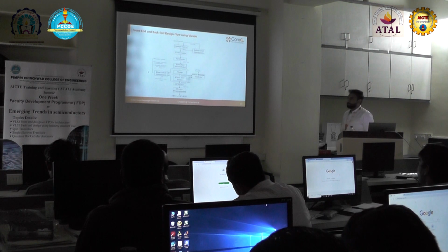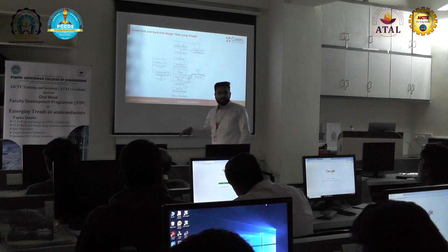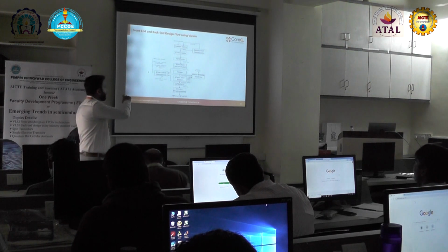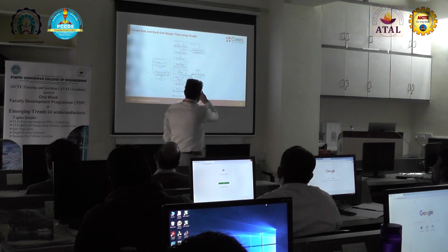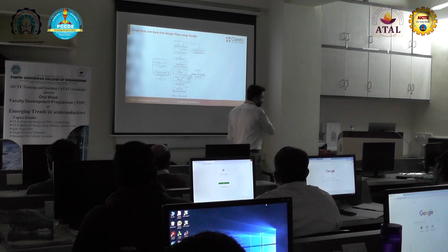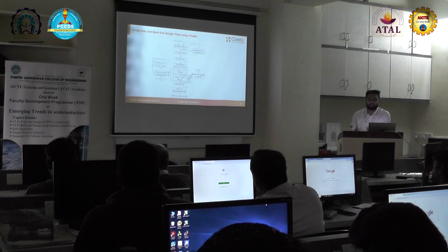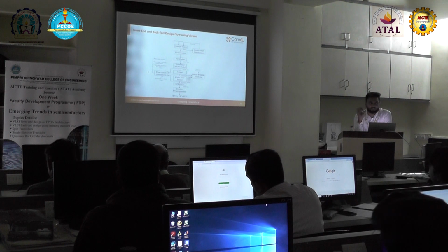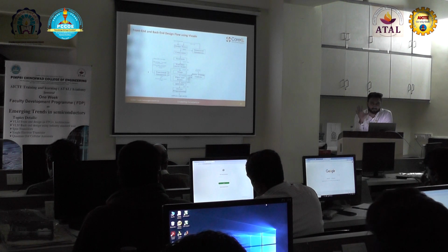So once the placement and routing has been done, the next step is we are going to generate the bitstream file, where this bitstream file has the information of the reports generated from the implementation. Whatever the implementation reports are, after that they are put in the bitstream file. This bitstream file is readable by the FPGA. This file will be taken out to check the functionality of the code. So we put that generated bitstream file onto the FPGA board, then we check the functionality.